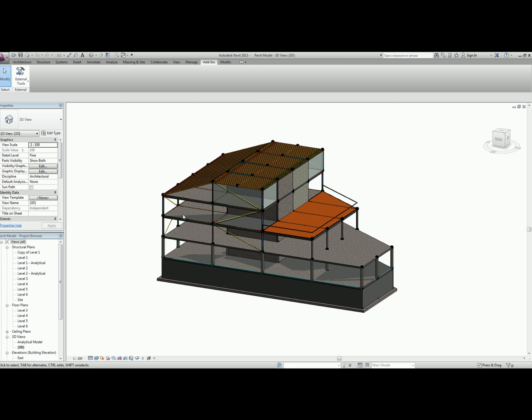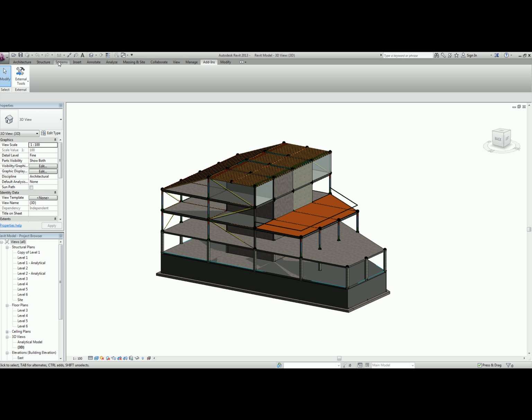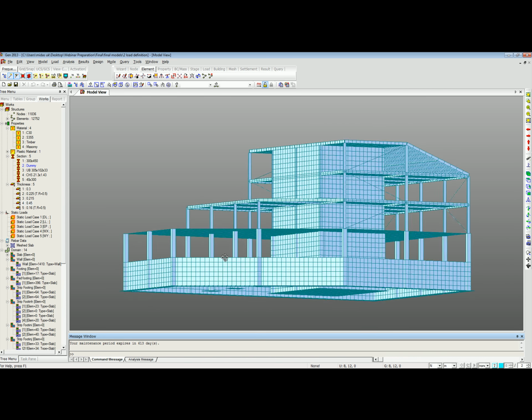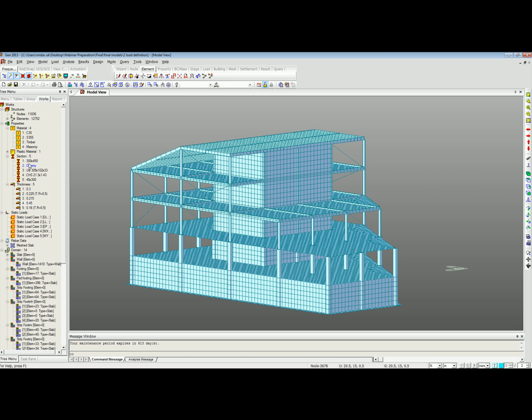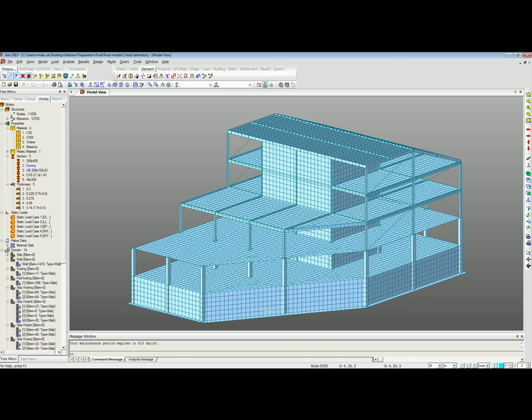You can see here the Revit model, which has come from the architect, or perhaps you've used it by the structural engineer. This is actually in Revit Structure. If we go to the external tools function, you'll see a direct link. Select that, export to midas Gen, and then what happens? It comes straight through into midas Gen. Everything comes through: shear walls, slab openings, all the section properties come through, as we can see on the left hand side in the works tree. No data's lost.